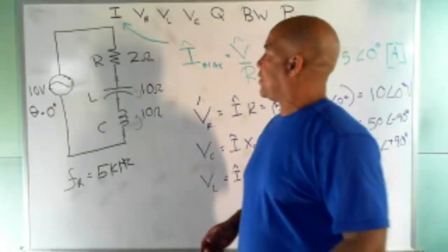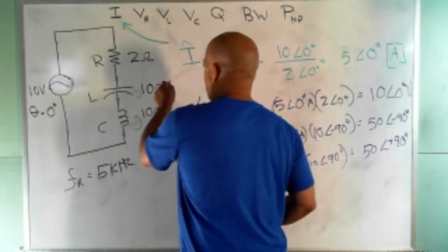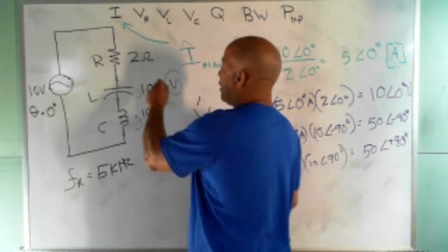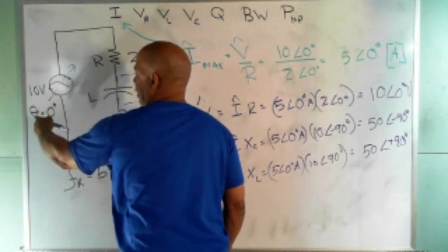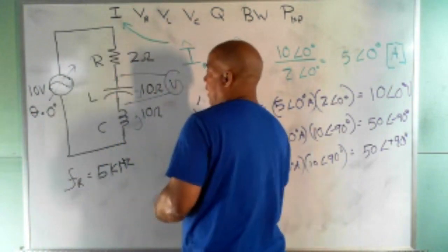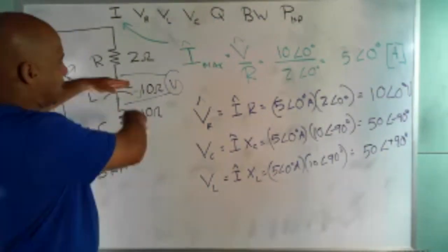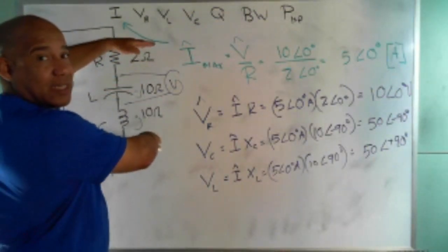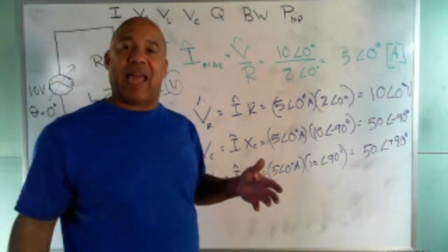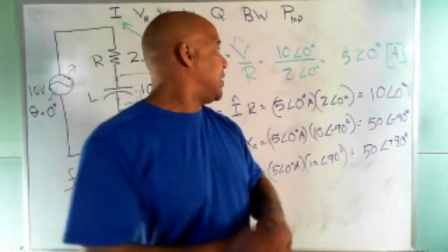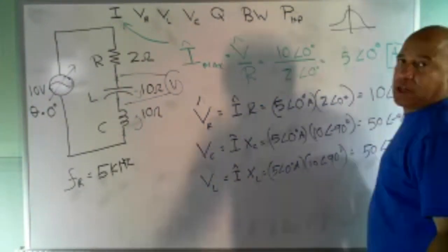If I had this circuit, I can take a voltmeter on AC and hook it to here. And say I vary the frequency. As I get closer and closer to resonance, the voltage amplitude will rise, and if I go past resonance, it'll start to shrink. So if we were actually doing this in the lab, you wouldn't see the resonant curve like this. This is the way we think about it, but you wouldn't see that curve on the oscilloscope.